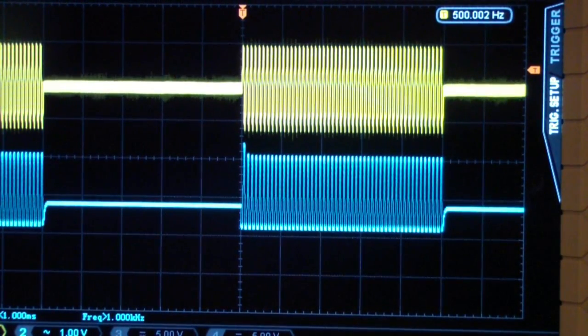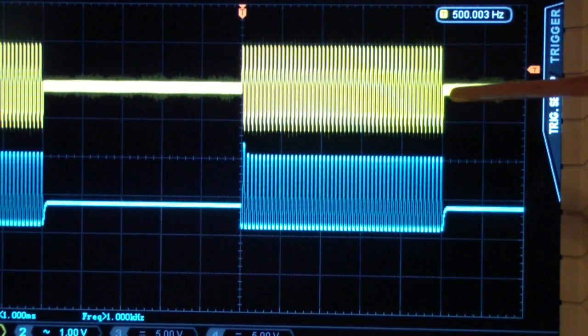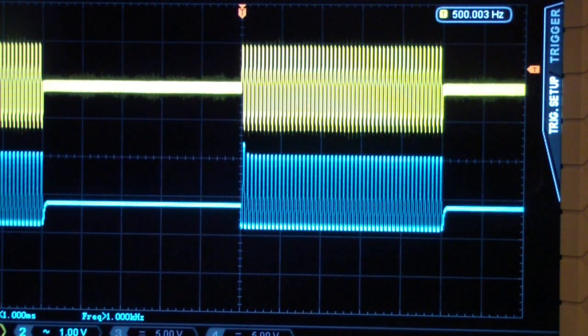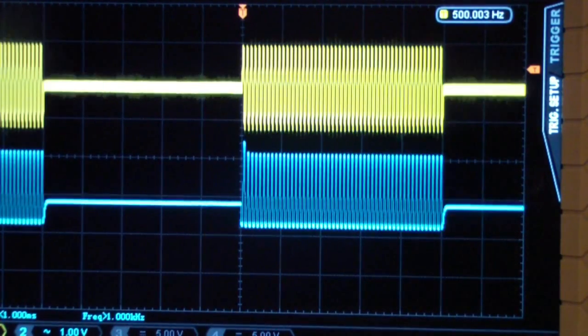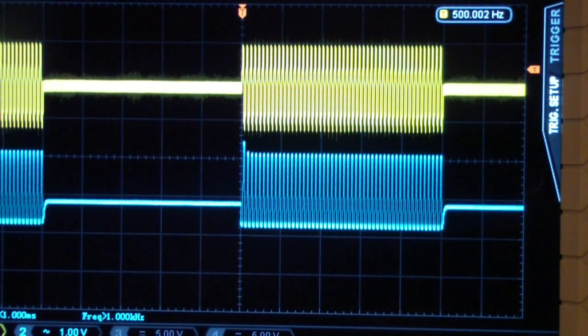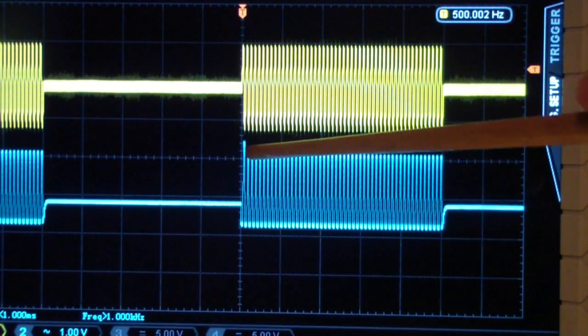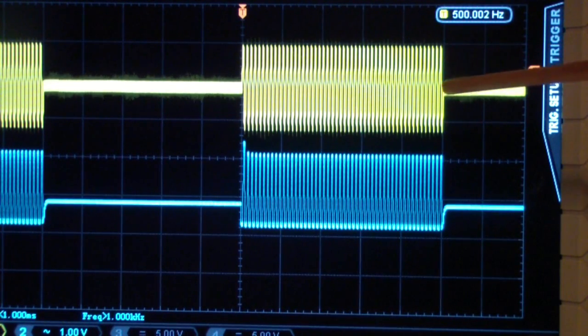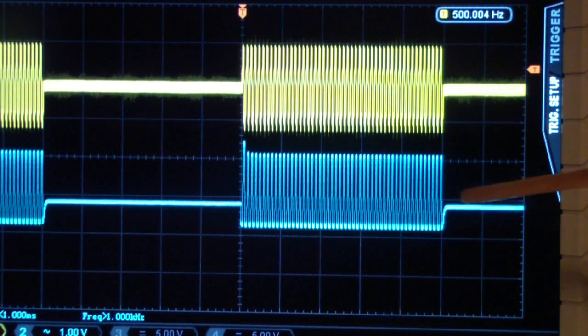And let's take a look at what it looks like on the oscilloscope. What you see on the oscilloscope is the input tone burst here in yellow and the output tone burst in blue. Now I have deliberately offset the amplifier to create clipping on the negative edge. What you will find with some amplifiers is not just that you get some distortion on the input as this shows, but also when the tone ends, you can sometimes get ringing in the output.